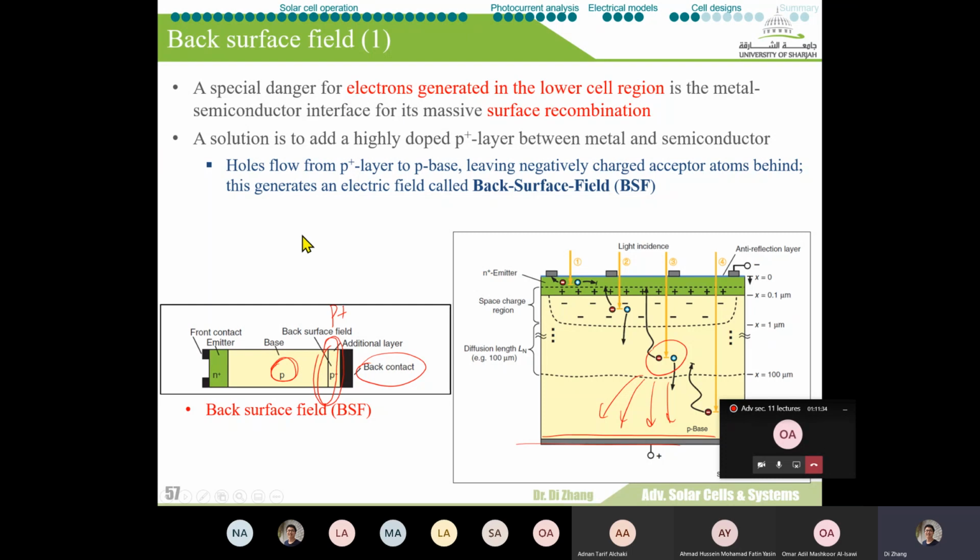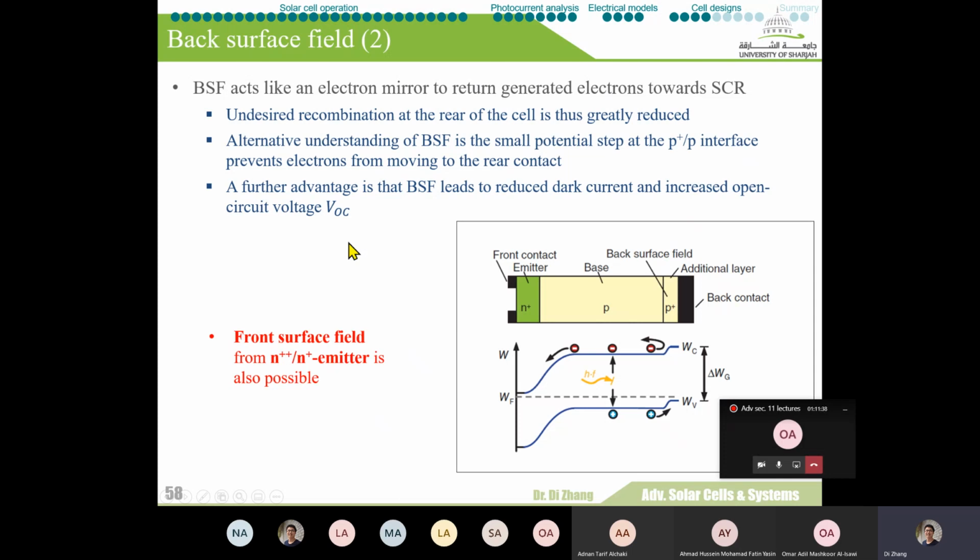If you look at the energy band diagram, by inserting an additional layer here, we know that naturally, if you plot the electron energy diagram from the p-n junction, there is typically a slope or a bending from the p-n junction. A very big jump because we're using very different materials on both sides. We're talking about n+ to p. But then if you insert a p+ here, it's going to be very similar to a p-n junction, but the energy band bending will be much smaller.